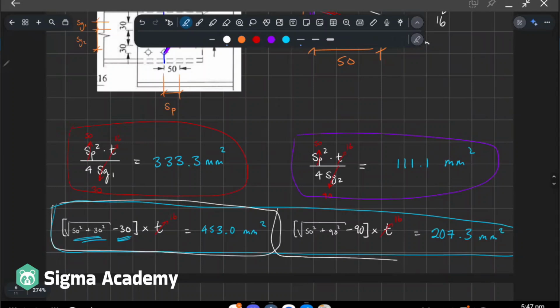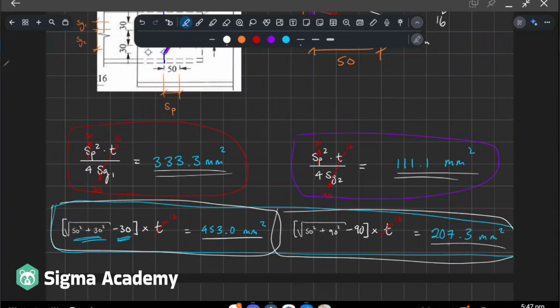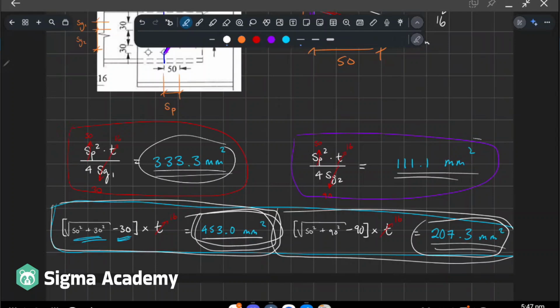It's here and here. And you can basically see that the numbers are comparable, but they're a little different, right? So if you do it just based on geometry, you'll probably give the section too much AN. The AN will be too big and it will be unconservative. So this is the conservative area that you get back from those diagonals, essentially.